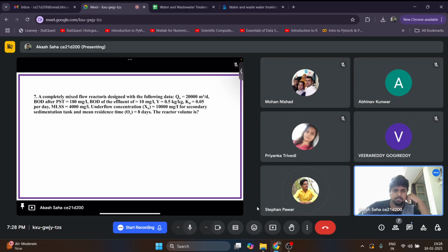Yes, sir, V is equal to 2000 multiplied by 8 days. No, no, not like this. The Q is 20,000. And 8 days is the mean cell residence time. It is not the HRT. HRT is different. HRT is not given in the question.